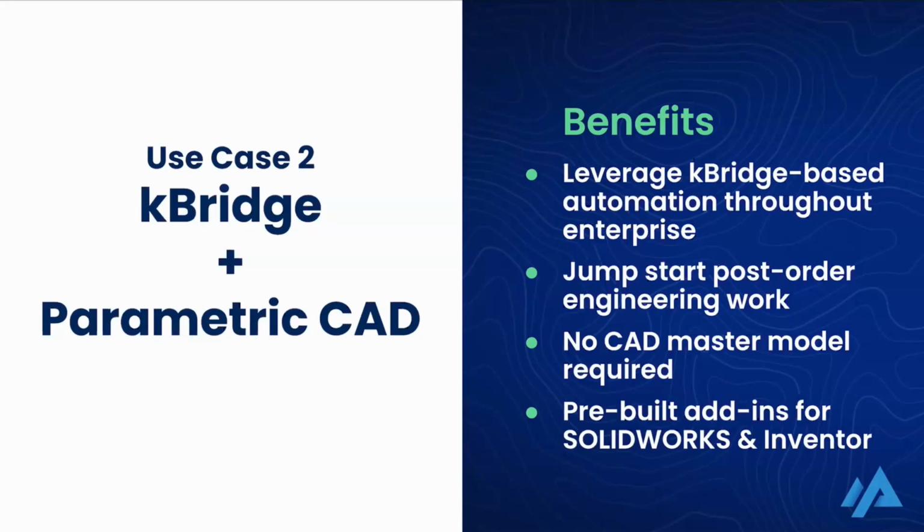That external system could be a homegrown program. It could be a system like kBridge, but ultimately, you're defining parameters within a CAD system that can then be automated because you're feeding values to those parameters. I mean, there are even CAD systems where, through VB or some native tool, Creo had something back in the day called Pro Program, you could manually pull up a viewer and key in a number of values and have the CAD system automate itself. So it's really driving those parameters. Hopefully that helps a little bit there.